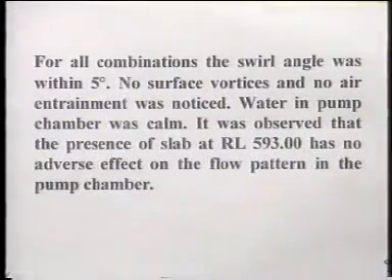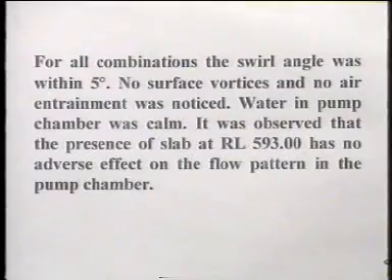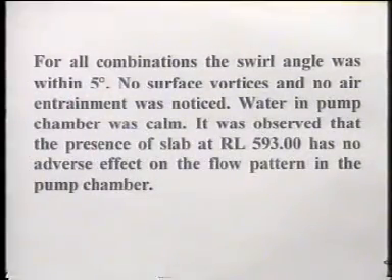For all combinations, the swirl angle was within the permissible limit. No surface vortices and no air entrainment was noticed. Water in pump chamber was calm. It was observed that the presence of slab at RL 593 has no adverse effect in the flow pattern in the pump chamber.